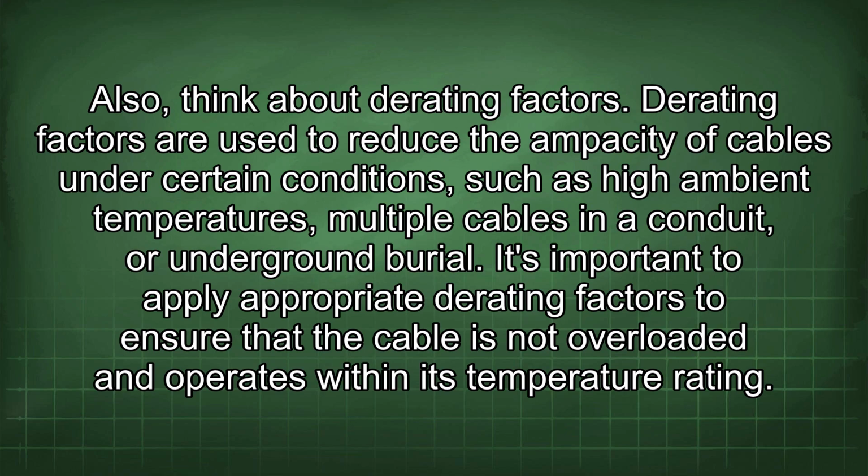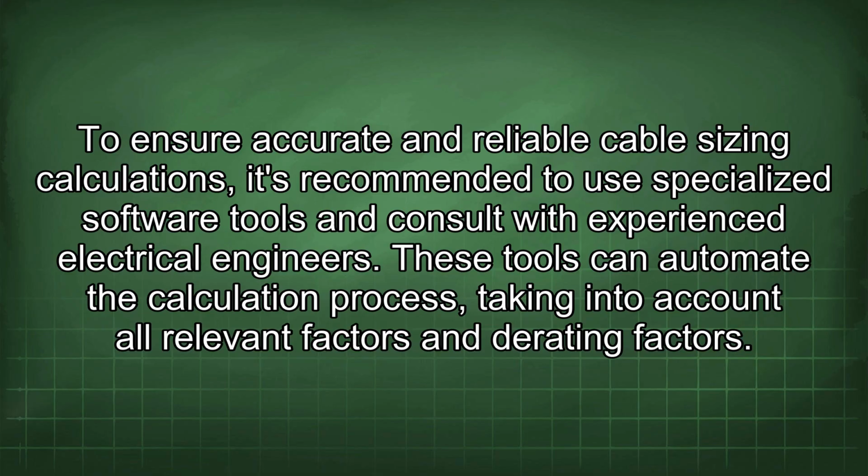Derating factors are used to reduce the ampacity of cables under certain conditions, such as high ambient temperatures, multiple cables in a conduit, or underground burial. It's important to apply appropriate derating factors to ensure that the cable is not overloaded and operates within its temperature rating.